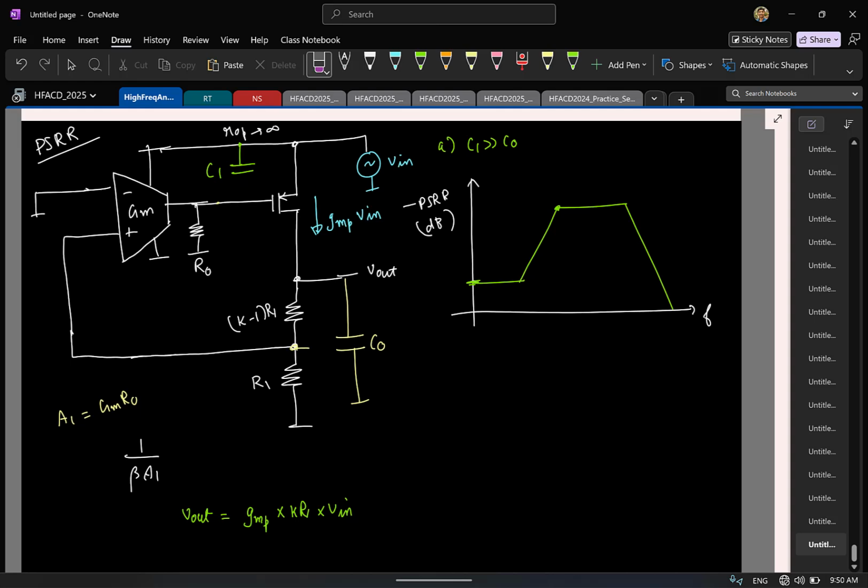So now if you do this, let's quickly see what will happen, right? Maybe I'll choose a different color. Let us say I do this. Okay. So now at high frequencies, this is acting like a short circuit. So now what can you say about VGS? VGS is 0, so what can you say about the current? What will be the output? Ideally it is 0, but in practice you also have a gate parasitic capacitor from this to ground. That is a parasitic capacitor of this MOSFET. So it won't be exactly 0, but yeah, something will be there.